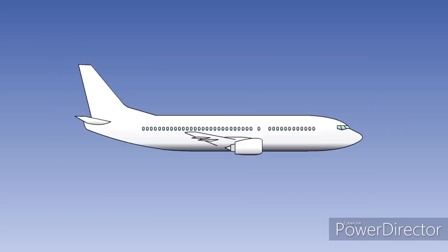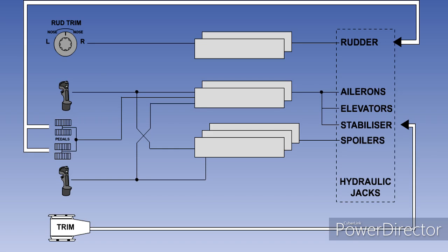The Airbus A320 fly-by-wire system is a fairly typical system, so we will now take a look at its features. There are 7 computers and 3 hydraulic systems looking after the primary flight controls. Each primary flight control has 2 hydraulic actuators, each fed from one of 3 independent hydraulic systems.